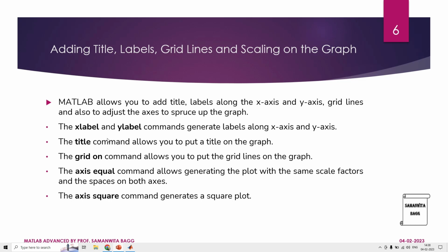Now we are going to talk about adding titles, labels, grid lines, and scaling on the graph. MATLAB allows you to add a title, labels along the x and y axis, grid lines, and also to adjust the axis to spruce up the graph. The xlabel and ylabel commands generate labels along the x and y axis. The title command allows you to put a title on the graph.